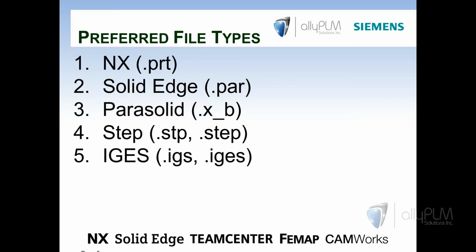This is a .igs or a .iges. IGES files are pretty universal but can produce some very poor data. We're going to look at an example of a bad IGES file later, and then how we can deal with that.